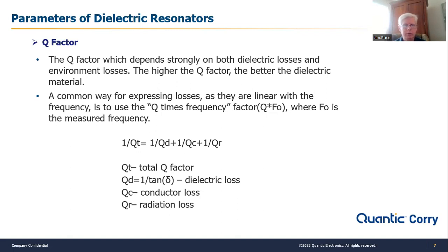So typically a bandpass filter is limited to maybe 2% bandwidth, something like that, 1 or 2%. In other words, if you were resonating at 1 gigahertz, your bandwidth can only be about 1% of 1 gigahertz, which would be about 10 megahertz, maybe 20 megahertz, something like that. They're going to be fairly narrow band.